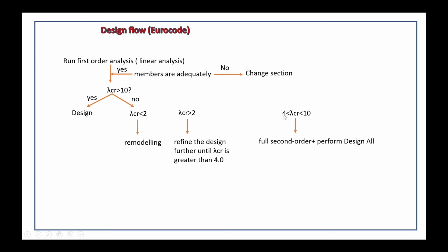You can limit it to 3 to 10. Now I limit it to 4 to 10. If you calculate lambda critical is greater than 4 and lower than 10, you can do full second order analysis and design. So you can check it.